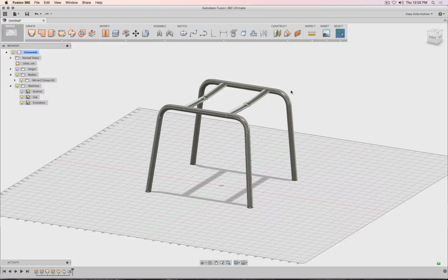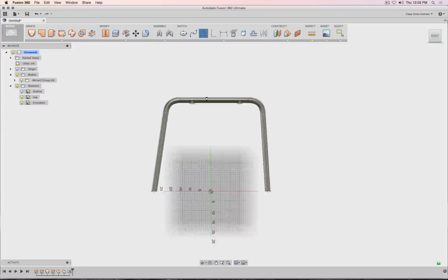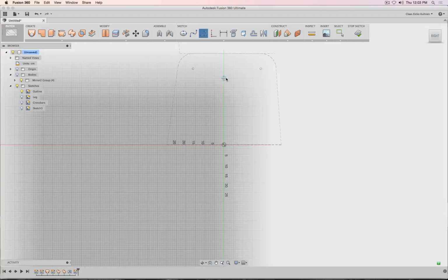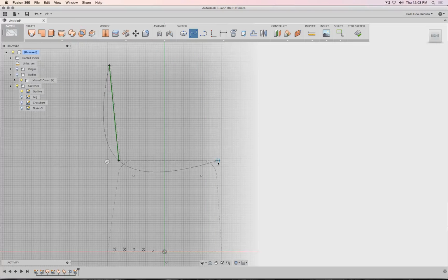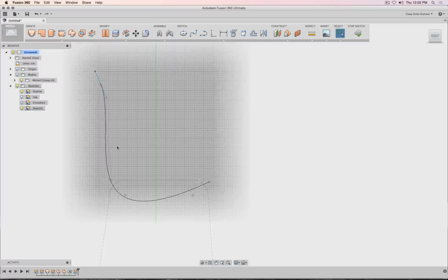Because in this sketch, it's time to actually take a look at how we can create our wood shell. Should be a bent plywood material. So I go to side view, create a sketch somewhere here. Maybe I'm hiding my bodies for the moment, and just show me my original sketch as a reference. And I can work with a spline. And I think I only need maybe 3 points there. Sketch is not visible. Oh, there. Okay. And then I can go ahead and maybe move those handles a little bit to kind of sculpt a shell I would be looking for.